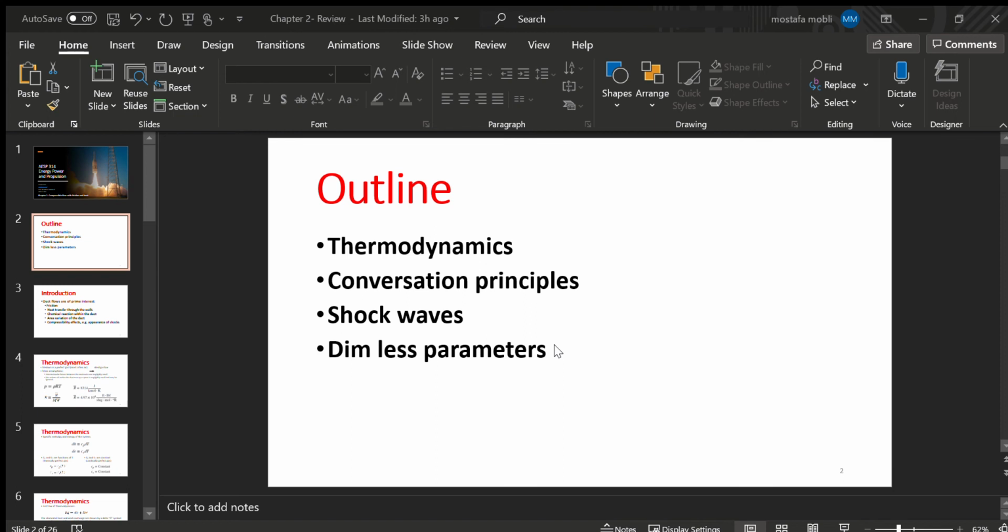And I wanted to go through the proof of the equation for the speed of sound. I think I have enough time. So essentially, let's say you have two states before and after a sound wave that is moving with a speed. If you simplify the continuity equation, or the conservation of mass equation, this is what you're going to get: rho u is equal to rho plus the change of density, multiplied by the velocity plus the change of velocity. That's after and before the sound wave, right?